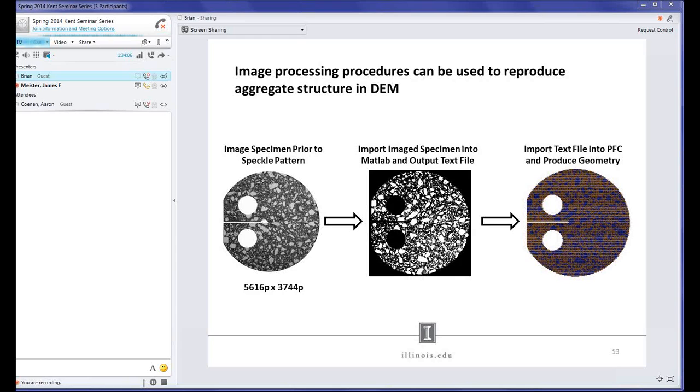Yeah, I would think that the bond then between the aggregate and the strength of the aggregate would become a big issue. And it results in the initiation of that crack. Yeah, and I think that's been seen not only with DCT tests, but also SCB work that was done by a lot of people in this room as well, and Cosmin, who did a lot of work with high RAP mixes with base courses. So yeah, it's a definite concern when you start to have large aggregates.